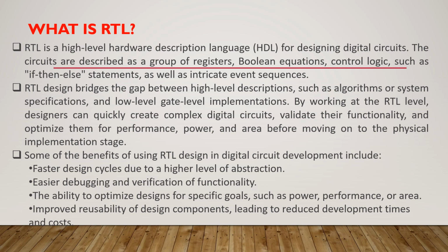Some of the benefits of using RTL design in digital circuit development include faster design cycles due to the higher level of abstraction, and it is also easier to debug and verify the functionality of your intended design. We also have the ability to optimize the design for specific goals such as power, performance, as well as area, depending on your applications. It also improves reusability of design components, leading to reduced development time and cost. So these are some of the key benefits of RTL design.